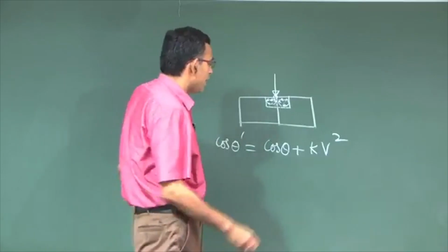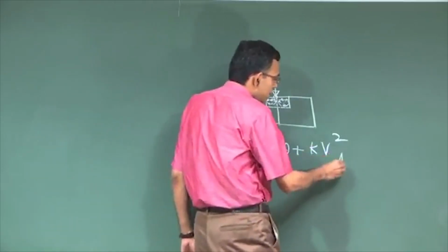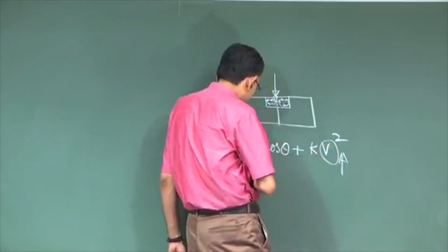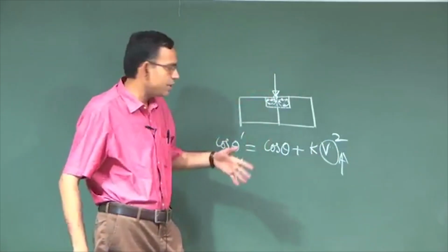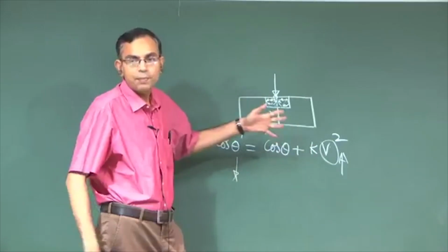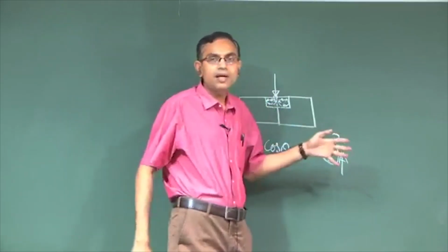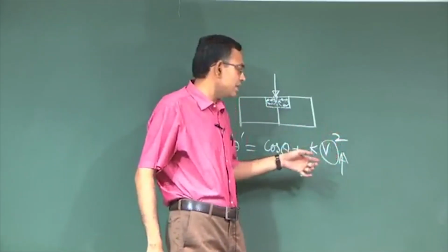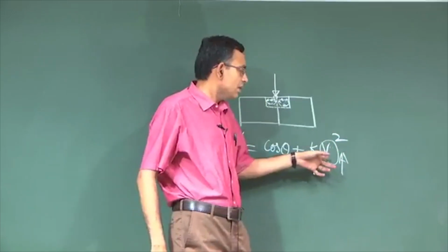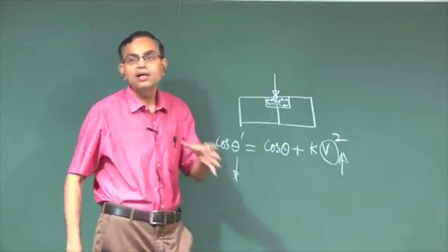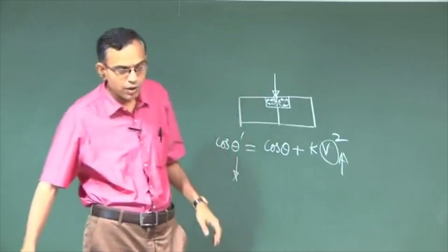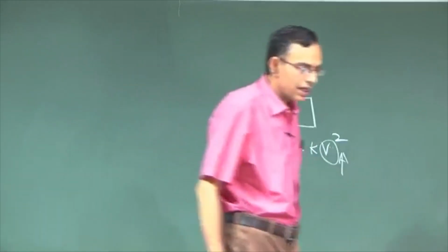This gives you the appearance that if you increase the voltage, the contact angle will go down and down forever, but it does not happen. It comes to a limit up to which, if you increase the voltage, it does not come down anymore. So, the contact angle comes to a saturation stage. This phenomenon is known as contact angle saturation.